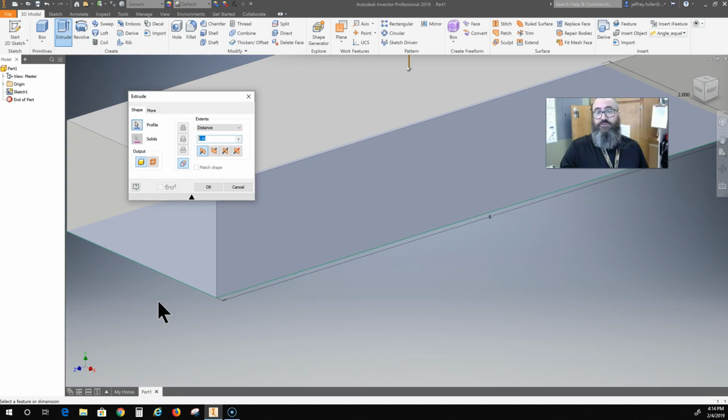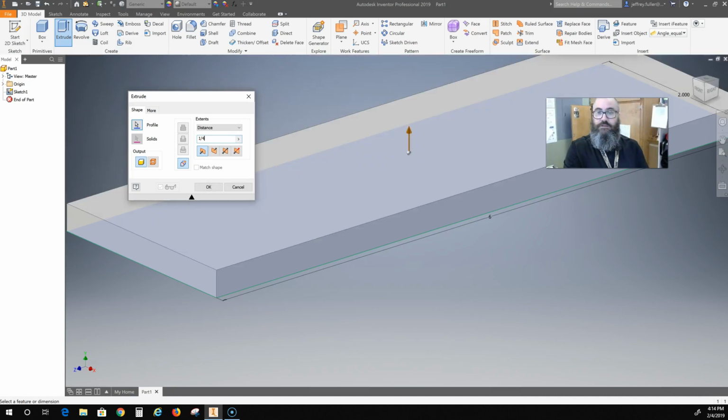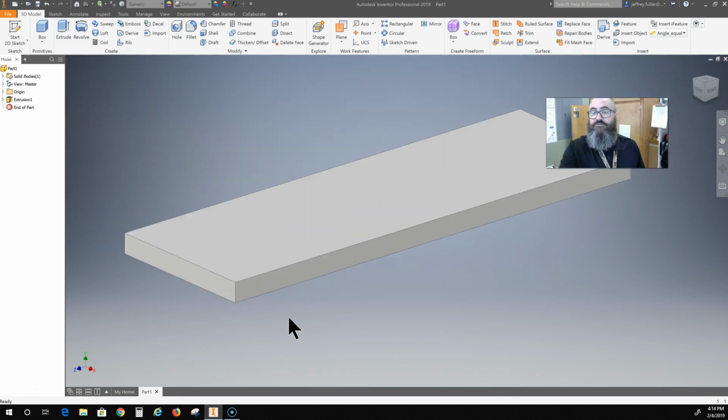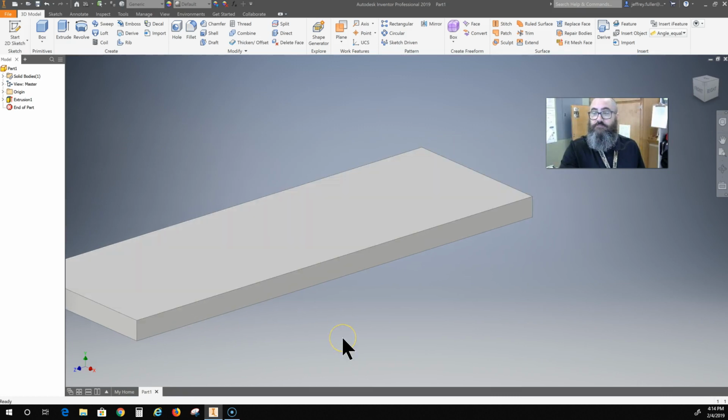I want these mullions to kind of stand out from the wall a little bit. So I'm just going to do 1/4 of an inch. And that's not any specific scale or measurement or anything like that. It's just 1/4 of an inch is all it is. So click OK, and now I have basically a 3-dimensional volume.